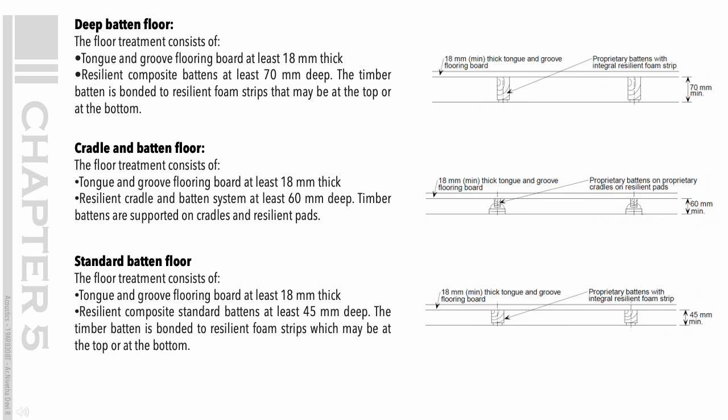Cradle and batten floor. The floor treatment consists of tongue and groove flooring board at least 18 mm thick. Resilient cradle and batten system at least 60 mm deep. Timber battens are supported on cradles and resilient pads.